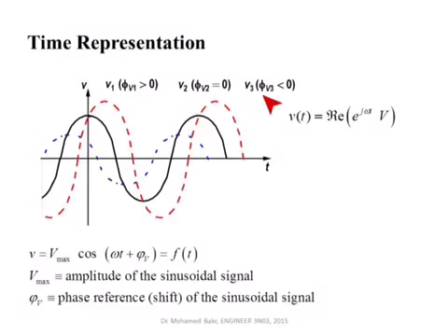So this one has a phase shift less than 0. And I explained to you, when you shift a cosine in the positive t direction, you are actually subtracting a certain phase from the angle of the cosine. You can see another cosine there, this blue cosine, this was shifted to the left. So it has a different amplitude, but its phase shift is positive.